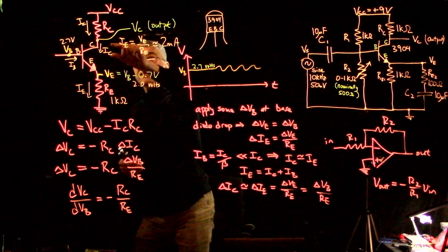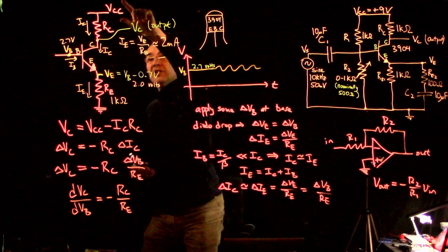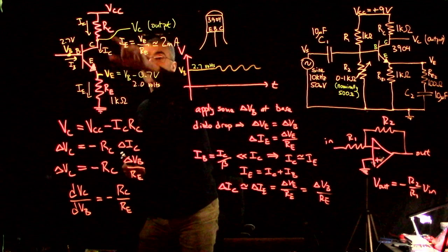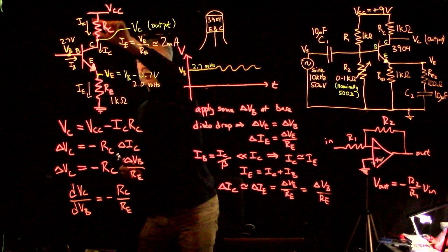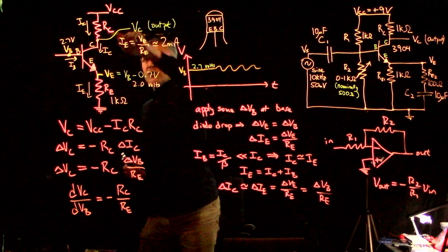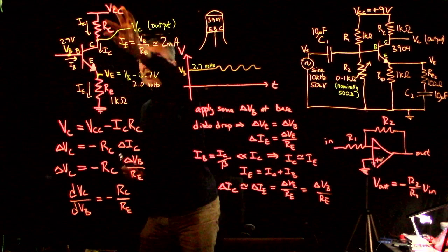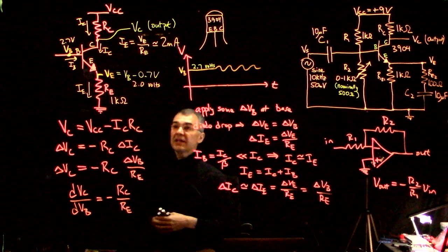And then if we put a resistor here, so we have a fixed voltage that we call VCC, and there's a resistor down to the collector, and we take the output at the collector, then when this current goes up the same amount, because this is a fixed voltage and this is a resistance, this voltage goes down in proportion. And then we can make this ratio of two resistances such that we get the voltage gain that we want.